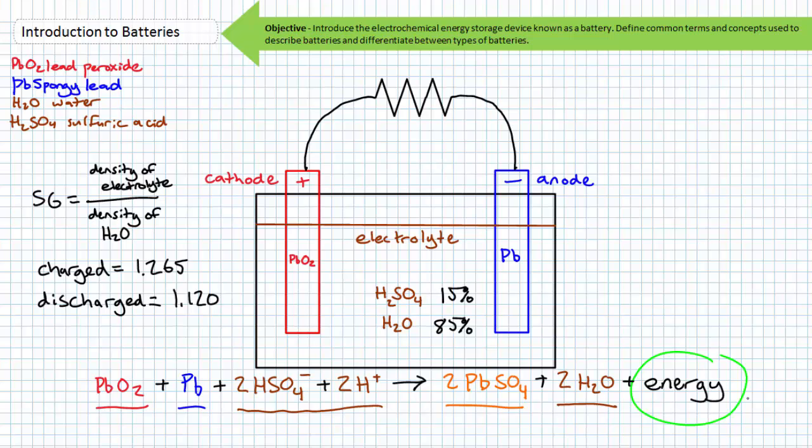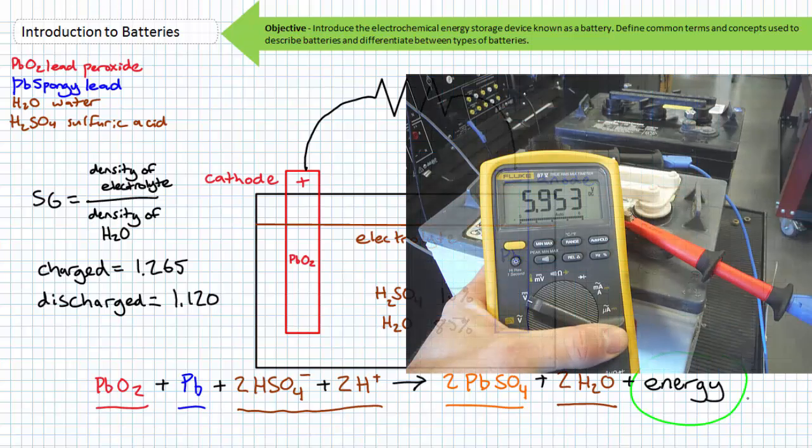The hydrometer readings, although an accurate means of directly ascertaining battery state of charge, are not exactly the safest and most convenient means of doing so. Not to mention that taking direct readings of the electrolyte concentration would be impossible for sealed batteries. It is for this reason that most individuals ordinarily resort to testing the open circuit voltage of a battery with a DMM in DC voltmeter mode as a means of indirectly ascertaining state of charge. Though not a direct means, the DMM is a substantially more convenient means of doing so, with significantly less chance of getting acid flicked into your eyes or dumped on your pants.